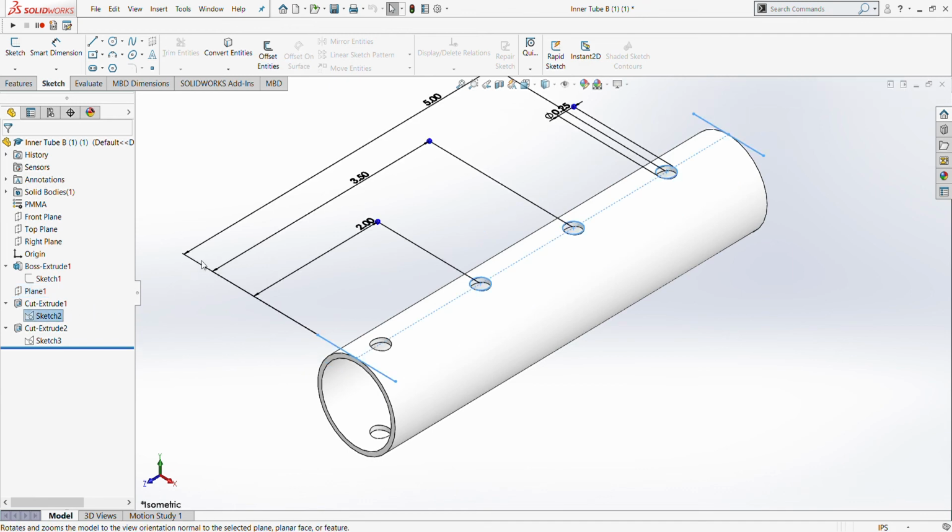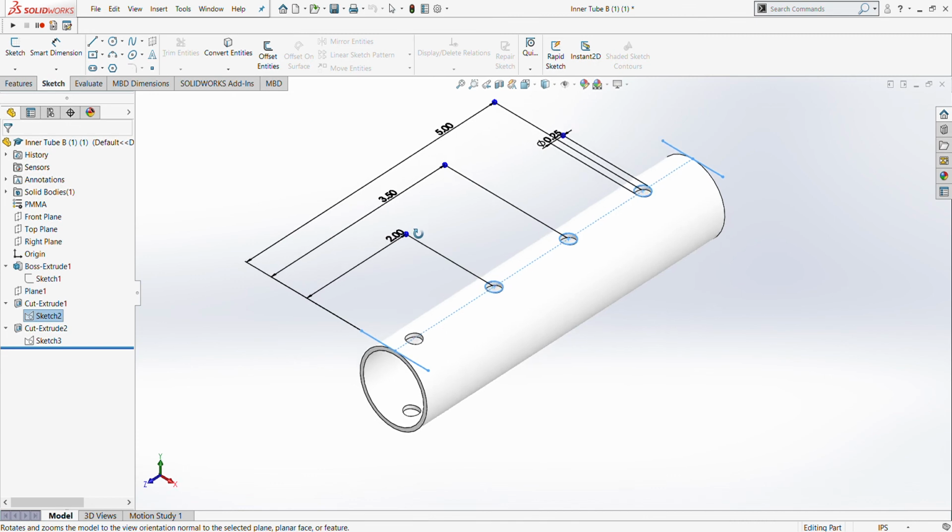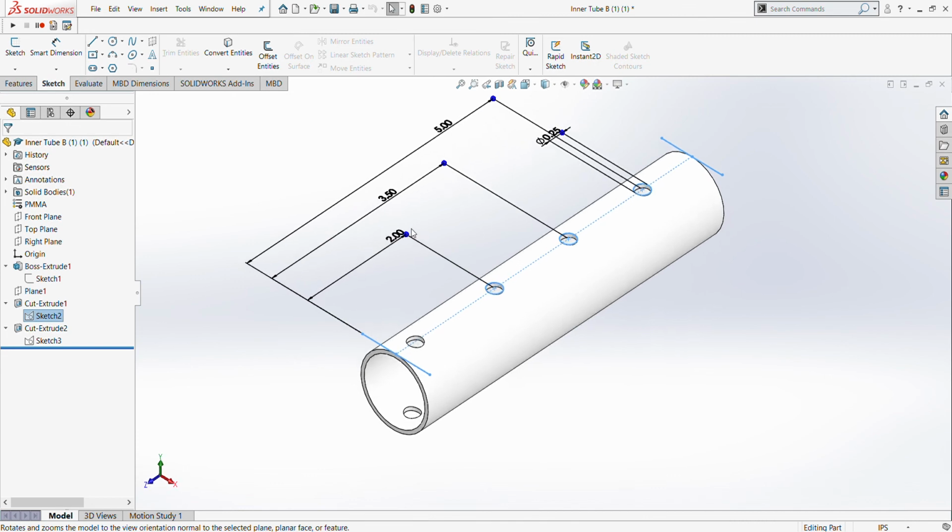On this reference plane, a sketch was made where 3 holes were placed, each 1.5 inches apart, again 0.25 inches in diameter for the size of the cotter pin that will pass through. The distance between the 3 holes was predetermined to create different size rod lengths when assembled together.